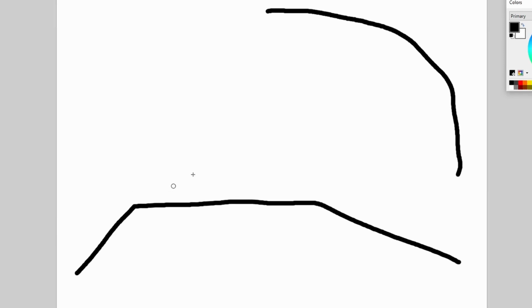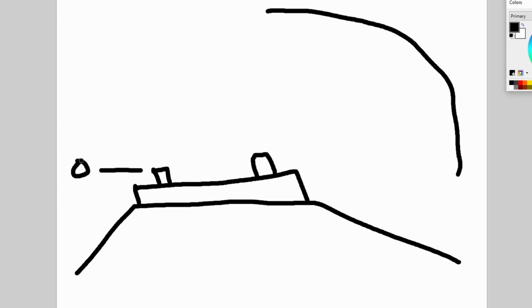But superelevation, if we have a big left-hand turn like this, right? Superelevation is where we take our track and our grade and we bias it towards that side. Say that we set our reference point here. So if we say that this is 0, that is no elevation, that is the height of the train, and we're going around this sharp curve, we might add a couple inches here. We might have 3 inches right here. So the outside rail of the curve over here is higher than the inside rail.